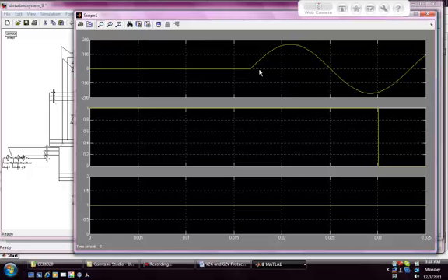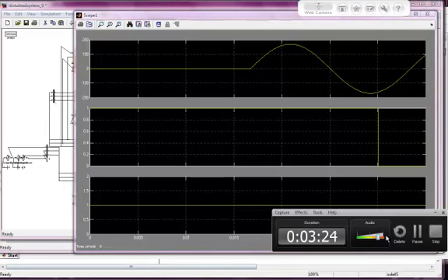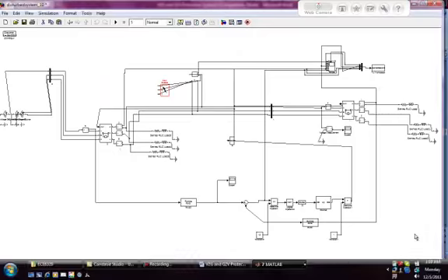diagram. Fault current is again on the top, then the breaker position of the electric vehicle, and the house breaker. Now the house breaker, if we have an extension up to maybe 1 second, we will see that it will trip right after the electric vehicle breaker trips, and this is shown in the MATLAB and CAPE program on the paper. Over here we have the differential relay.